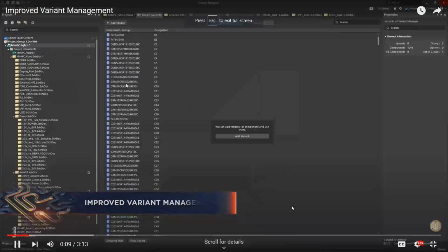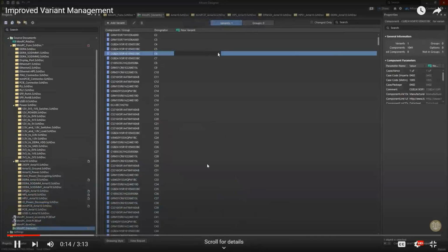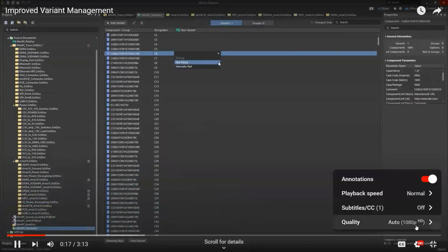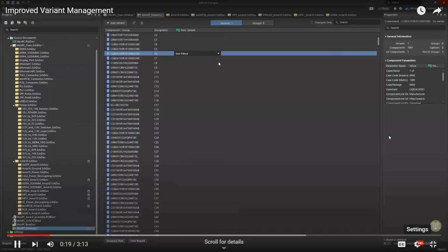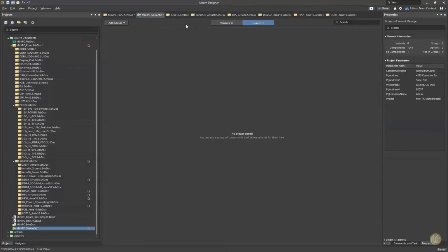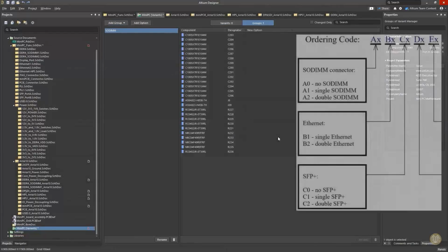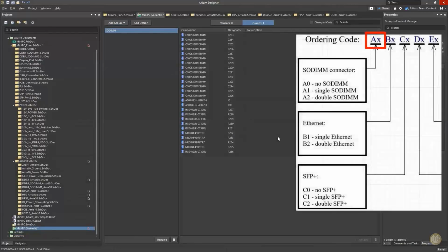As I told you, I don't have access to this version. Altium Designer offers both a new and legacy approach to design variants, where you can assign each component one of three states: installed, not installed, or replaced. The new variant manager's full power is realized with component groups. Groups are formed on the basis of schematic sheets, sheet symbols, or project component classes. Once a group is formed, a list of its components is created, and you can start to configure the options. Each option defines a particular state of the component group.